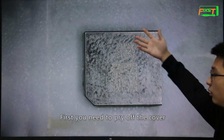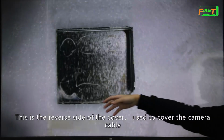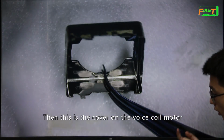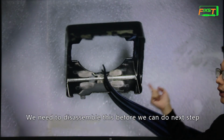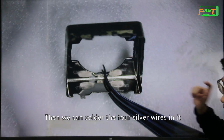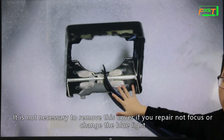First, you need to pry off the cover. This is the reverse side of the cover, used to cover the camera cable. Then this is the cover of the Voice-Coil motor. We need to disassemble this before we can do the next step. The cover needs to be disassembled to repair the shaking. Then we can solder the 4 silver wires in it. It is not necessary to remove the cover if you repair not focusing, or change the blue light.